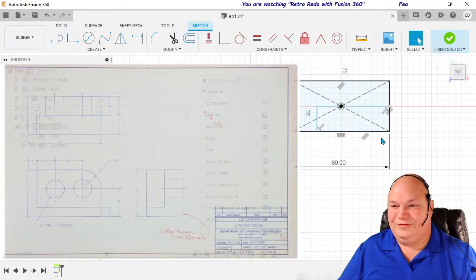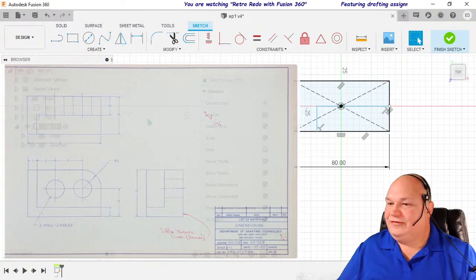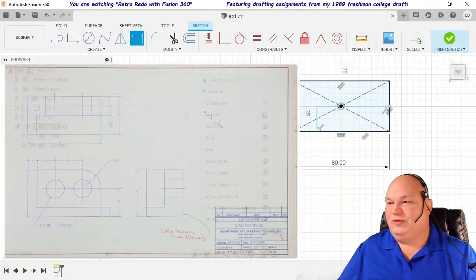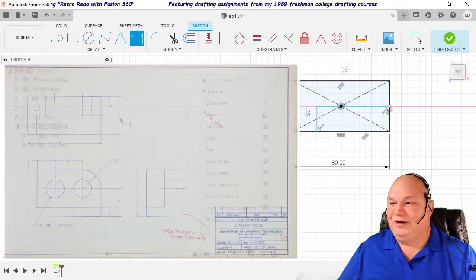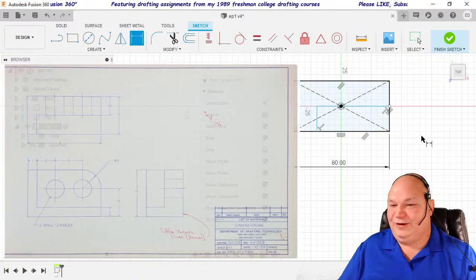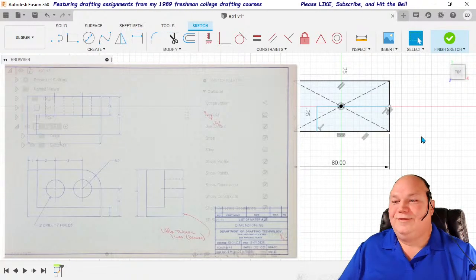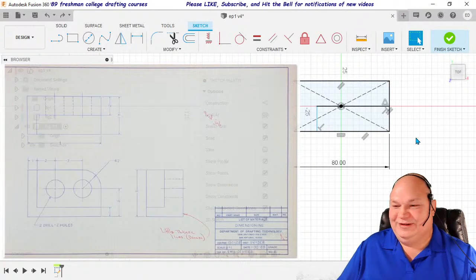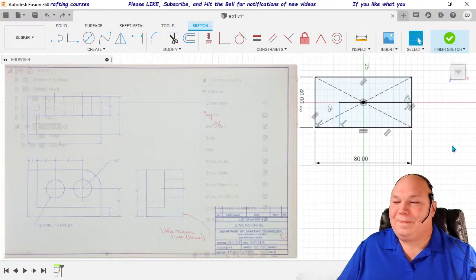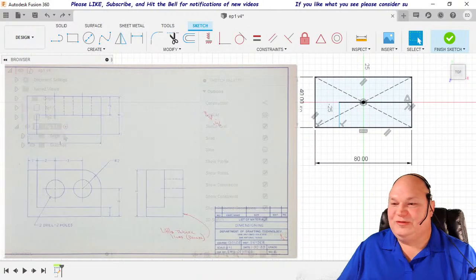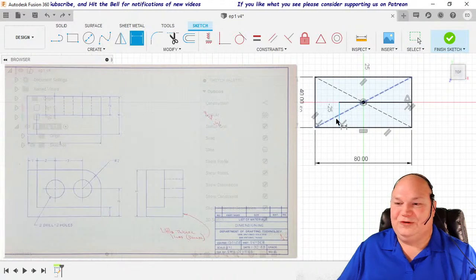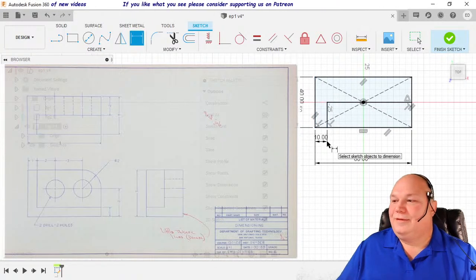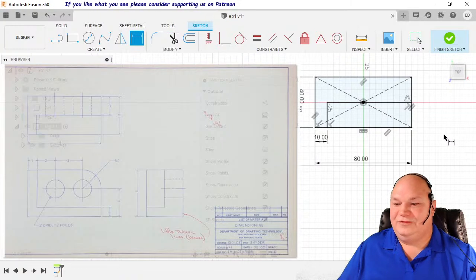But we can delete the constraint, as I said before. So now this distance here is, well, let's just put that in the dimension pile, since it is 2 by 4 and it is the center. So let me hit Control Z a couple of times, and okay, we're back, because it is supposed to be there in the middle of the object. Now this distance here is only supposed to be 10, so let's finish that dimension. There we go. Now we're ready to start doing some extruding.